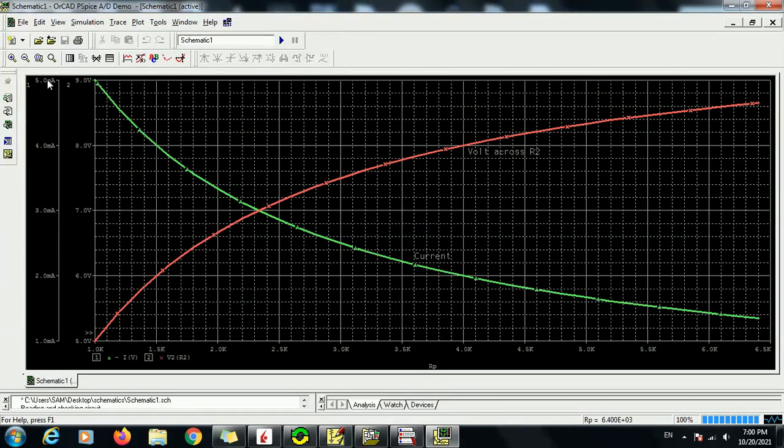So we start from 10 milliamps. However, because we have the R2 starting at 1 kilo ohm, we get half this value, which is 5 milliamps. And then we go downwards. The more we increase the value of the resistor R2, the more we decrease the current passing in the circuit.